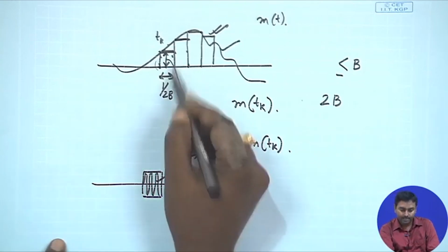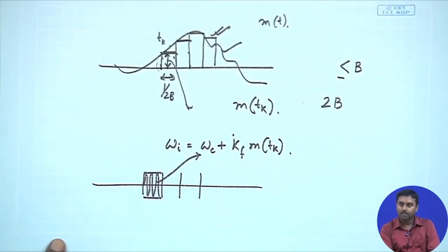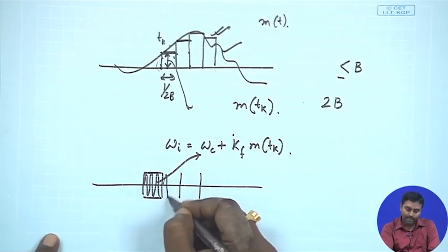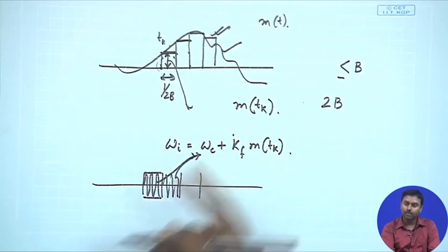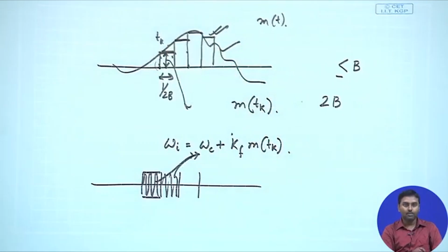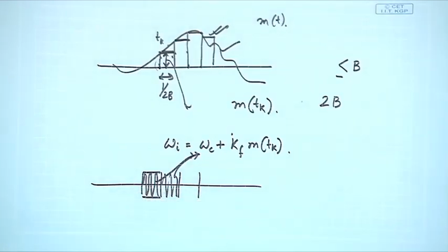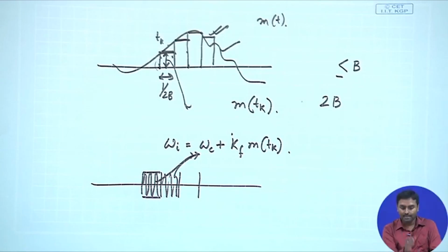I can just subdivide it into those pulses and modulate each with the frequency that comes out from here, whatever value I get at that instance. So this is a faithful representation of FM modulation, as I can immediately say from the way we are constructing it. The advantage we get is that we now have a pulse which is getting modulated at a frequency which is known to me.